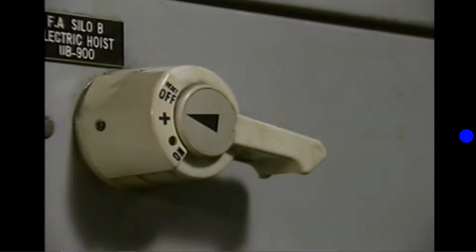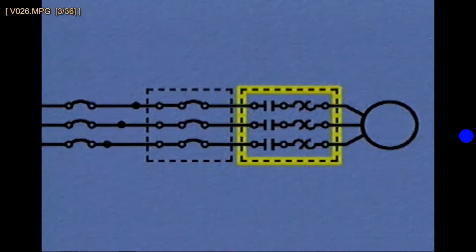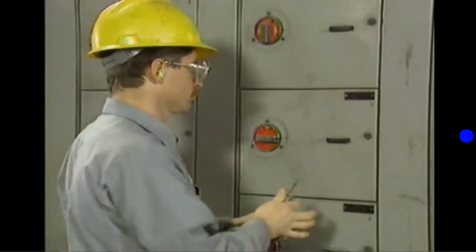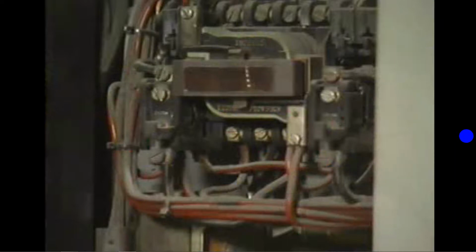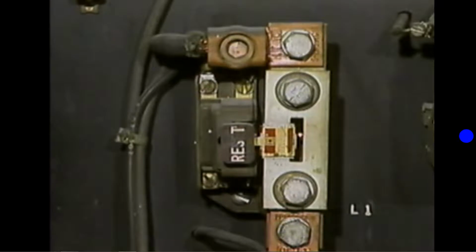To the right of the circuit breaker is a controller section, which is a motor controller. A motor controller is a device or group of devices that control and protect the operation of a motor. For example, a magnetic motor controller uses electromagnetic switches to perform control functions. In addition, the controller contains overload devices that operate to protect motors from damage that could result from overloads.